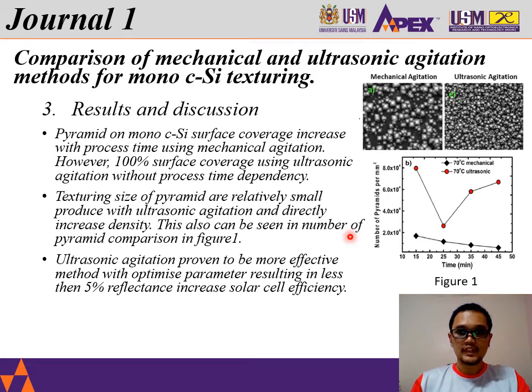In this picture on the right side, you can see the mechanical agitation under SEM, with a lot of empty space compared to the ultrasonic agitation, which is fully populated by the pyramid shape. We can also notice that the pyramid texturing size is relatively smaller on the ultrasonic agitation and bigger on the mechanical agitation.